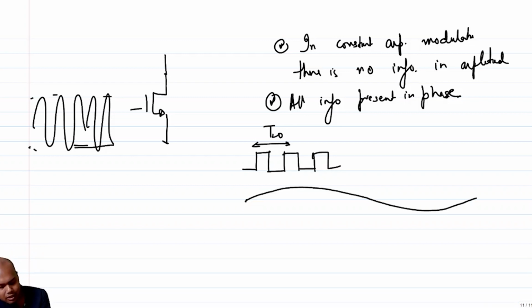In a square wave, when I go from one rising edge to another rising edge, I cover 2 pi, correct? So let's assume the second rising edge moves by theta degrees from 2 pi, then that theta is essentially the information. The amount of time your zero crossings differ by, which means the phase with which your zero crossings deviate from their ideal value, is essentially the amplitude of the baseband signal, so as to say, right?